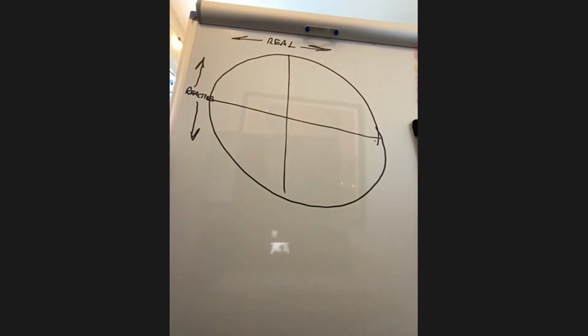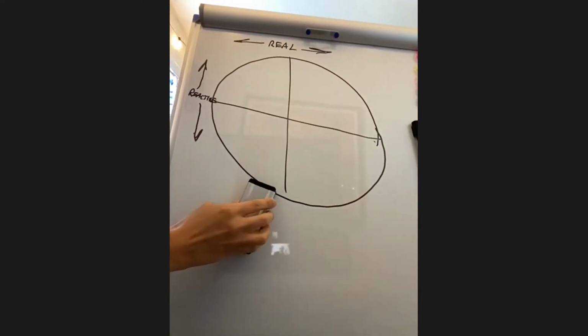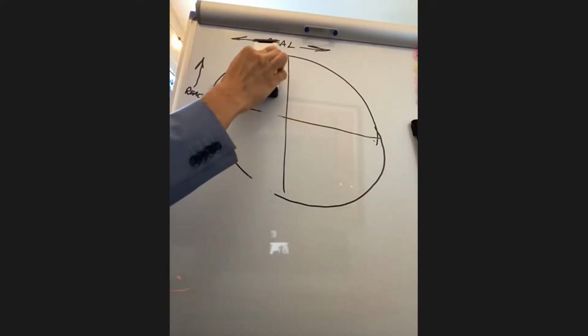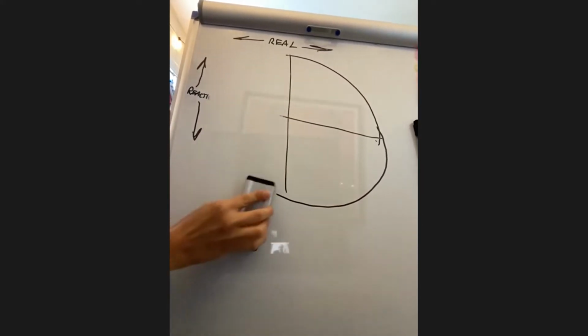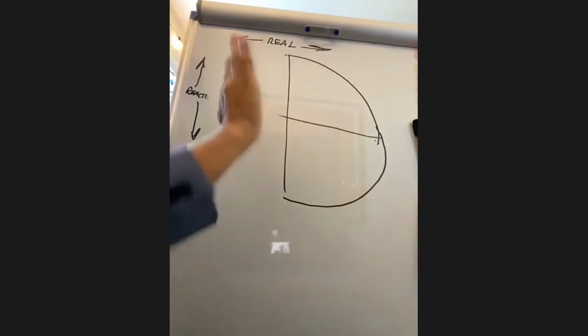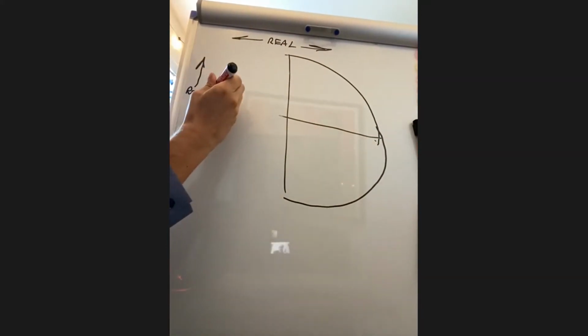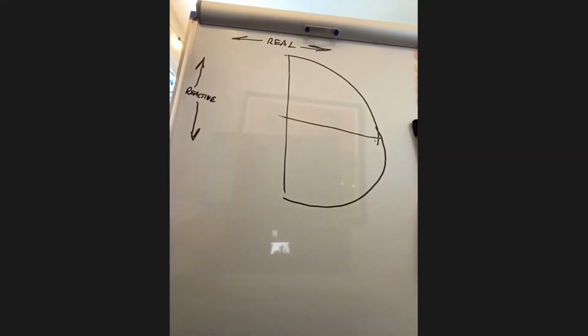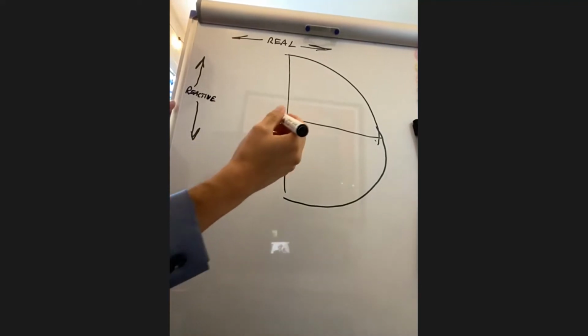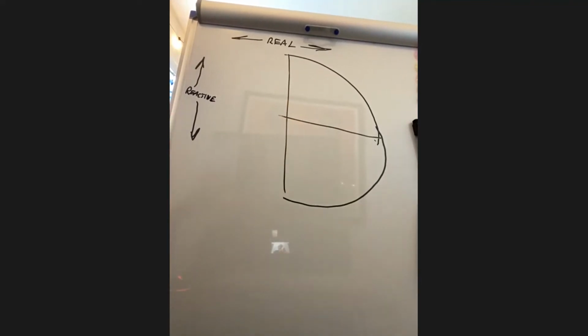When you are a smart inverter on a solar array, you're not consuming any power, you're just generating power. So this whole half of the circle just goes away, and really we're just talking about this half of the circle. When an inverter is producing power, generally it's just going to produce real power because that's what you get paid for, your kilowatt hours.